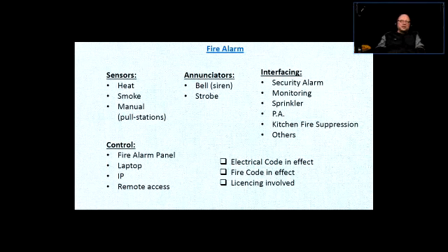So in this case, what are called dry sprinkler systems are installed, so there's just air in the pipes, and if one of the sprinkler heads is triggered, then the water from the main panel is released into the pipes, so it could extinguish the fire in whatever area that is. So there's a difference between dry and wet sprinkler systems.